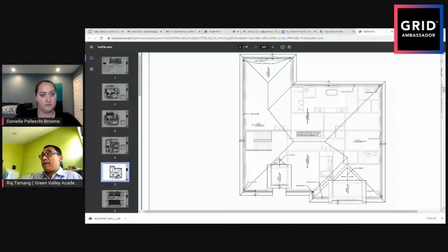So you have to have that minimum slope. So on the roof, you have a house and a big flat roof like this. I'm still showing the slope, how I have to divert the water from the roof towards the edges. And there definitely, I have gutters, downspouts, right? So sometimes you might have a concealed gutter. We can talk about that later. But sometimes, traditionally, you just have gutters around the roof perimeter, and you have downspouts bringing the water down to the ground. Right? So that information you still have to show on the plan.